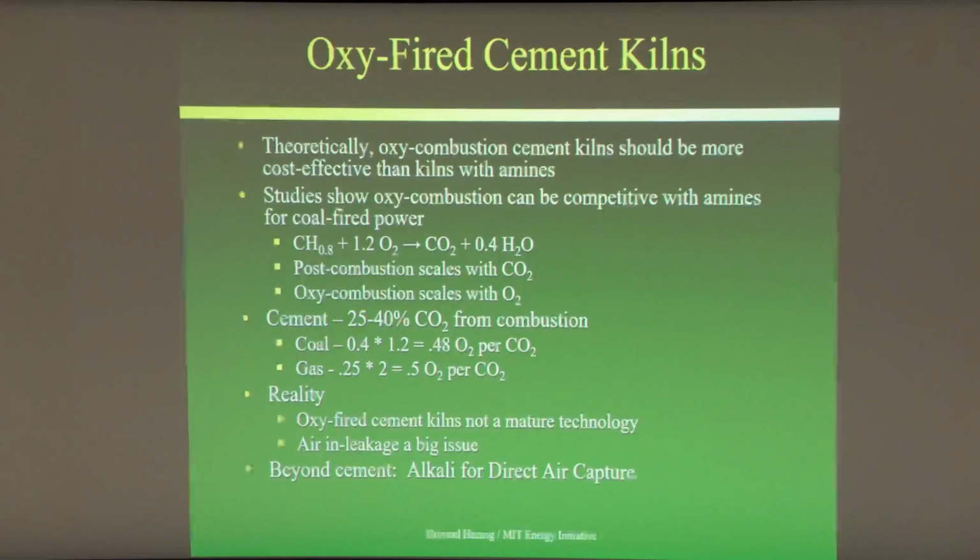The studies have shown that on a coal-fired power plant, oxy-firing can be competitive with amines. And if we look at a coal plant, you need about 1.2 molecules of oxygen for each molecule of CO2 that's produced. The cost of post-combustion scales with the carbon dioxide. The cost of oxy-combustion will scale with the cost of the oxygen.